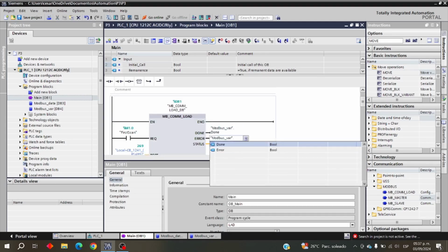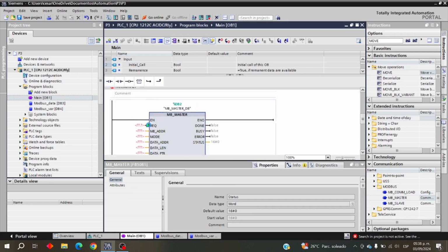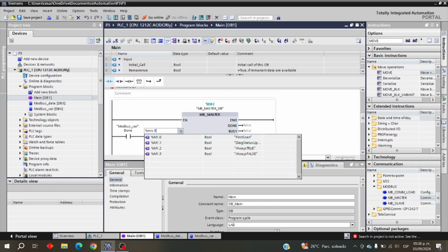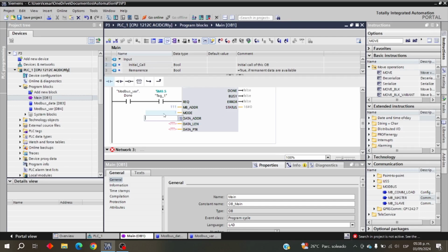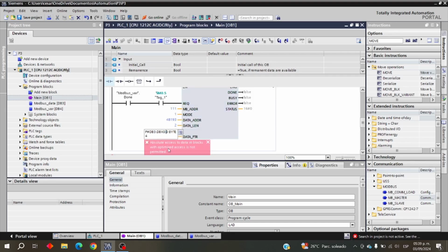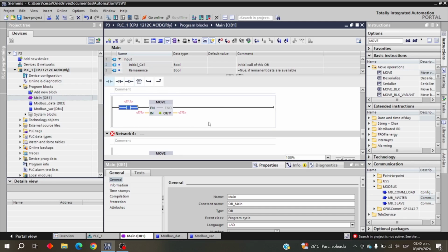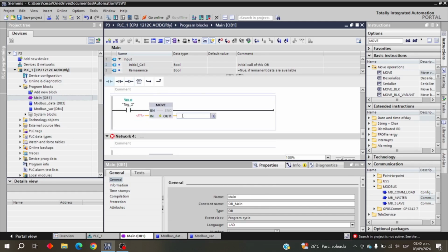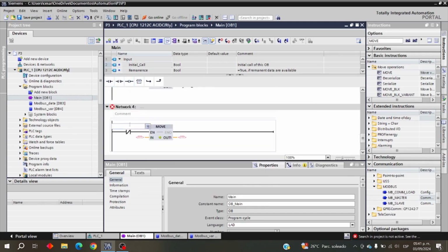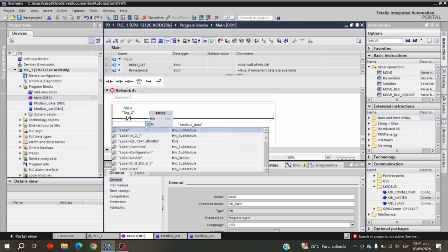Here we're setting information in the slave and in the communication block of the TIA Portal. Also, we're going to need two MOV blocks that will alternate their functionality to tell us that the communication protocol is going well.